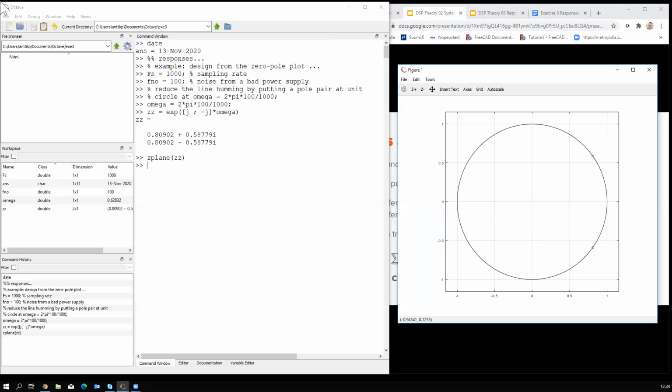Okay, mirror symmetry. Good, so those are the zeros. And now if we know that our actual signal could be DC, I can calculate the transfer function from that one and just put the poles at the origin. So this would be an FIR system, when the poles are at 0, a second order system.